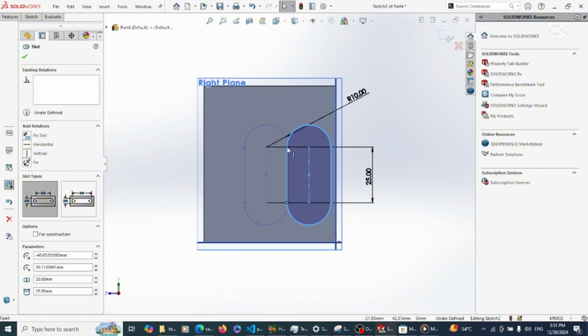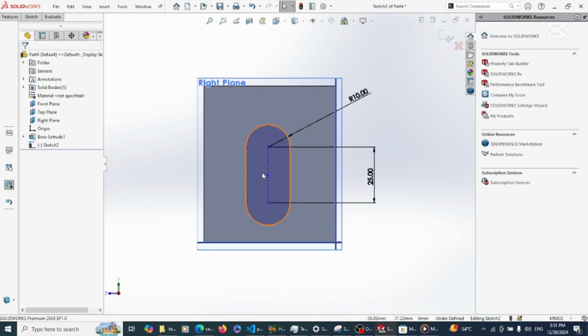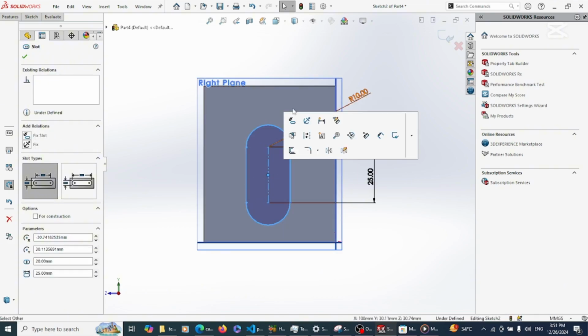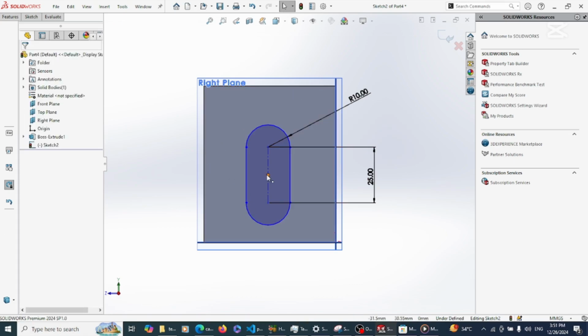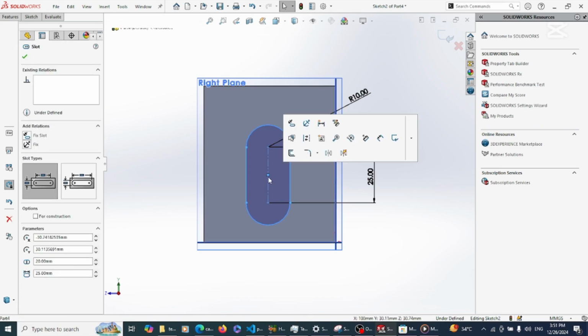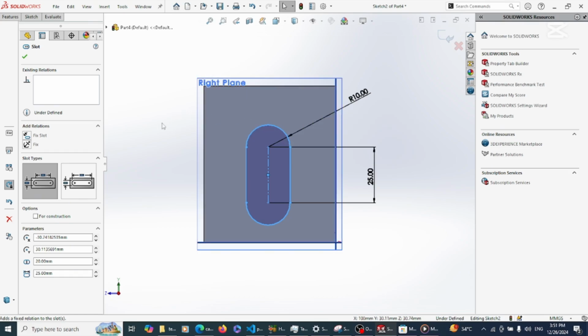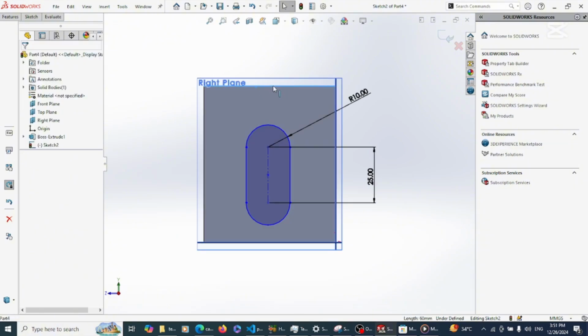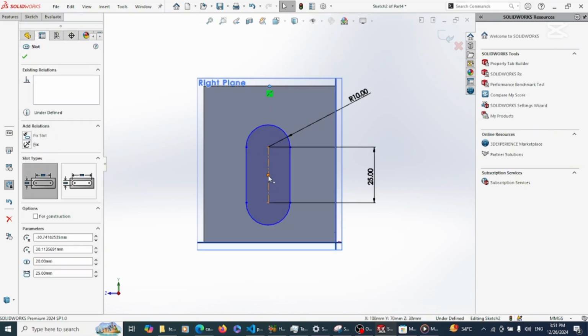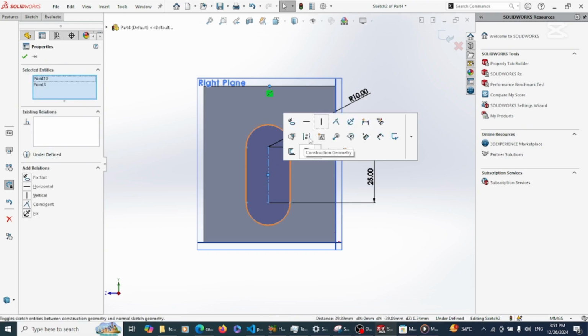I told you when you see things like this, try to move a line and see what's happening. Or you see that the whole sketch is moving around, meaning this guy is not fixed. So how do I fix this? I can try to pick the center point, and go here, find the center of this guy. Yes, this is center point. I pick this one. I hold control. Holding control, I pick this point. Good.